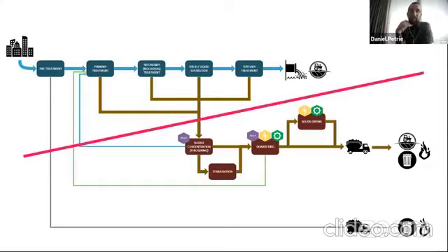The functionality of the liquid stream treatment processes dictates the quality of sludge that the sludge treatment processes receive. And then at the same time, the effectiveness of the sludge treatment processes determines the quality of the return streams, the filtrate streams, the centrate streams, these thin blue and green lines that are returning to the head of the works. So to keep them segregated, you've really got to build in a huge buffer in between the two. And that requires large storage tanks.